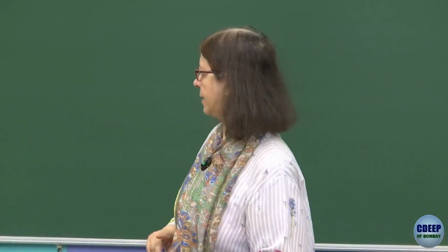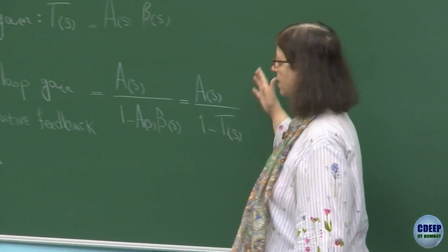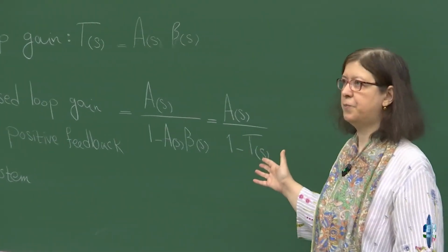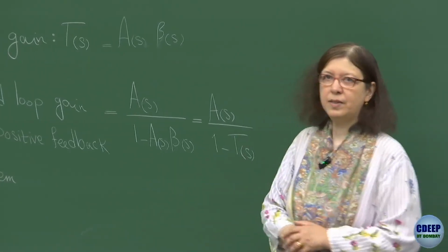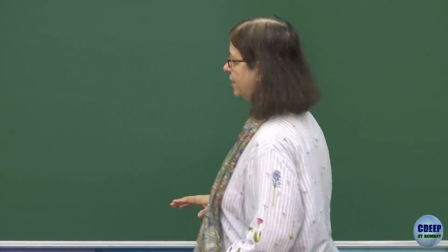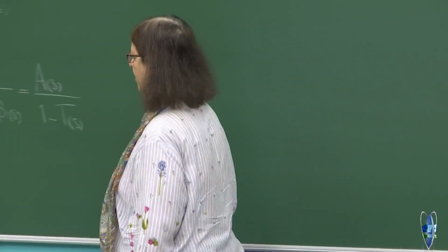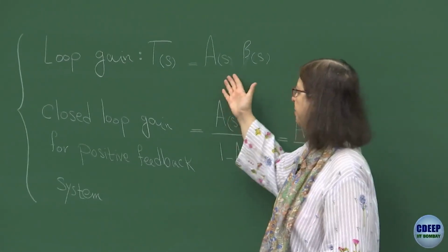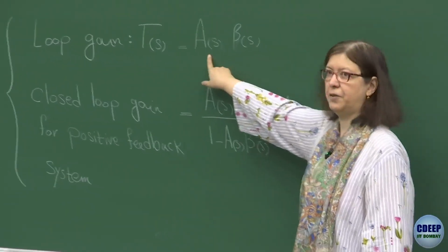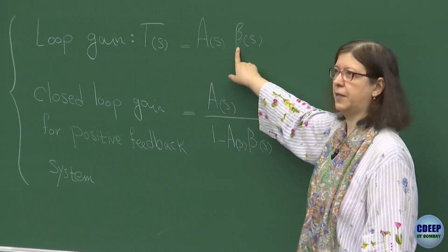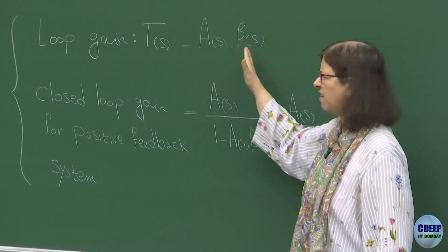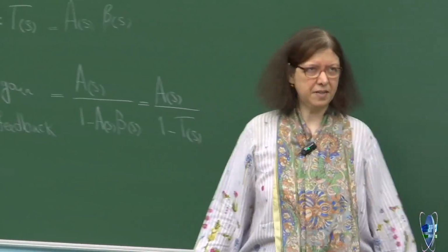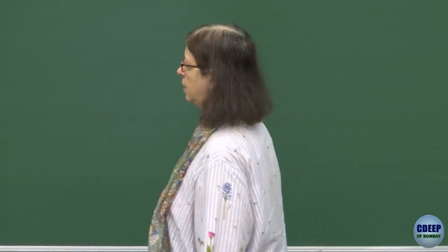Before starting that, I want to give a kind of closure to the discussion in the last lecture, which was related to the positive feedback within a latch or a regenerative circuit in general. When you look at a positive feedback system, you have a loop gain, which is the feed-forward gain A(S) multiplied by the feedback factor beta(S). Let's, in general, consider both of them as a function of S. So this makes it a very generic case.